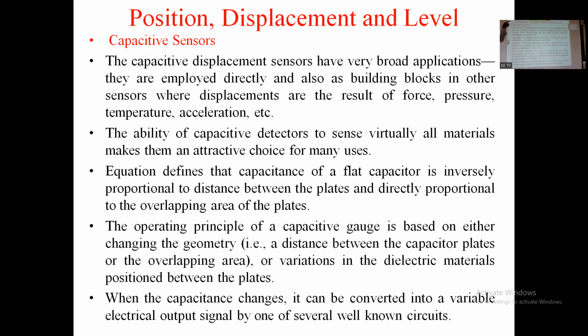If these are two plates like capacitive plates, and the distance between the two plates is reduced, it will be measured in the form of capacitance. Right? If force is applied to a flexible plate, the distance between the two plates will change. So if force is one of the stimuli, the distance between the two plates will change, and then a capacitor measurement device can be used.